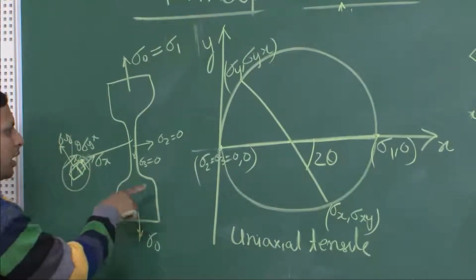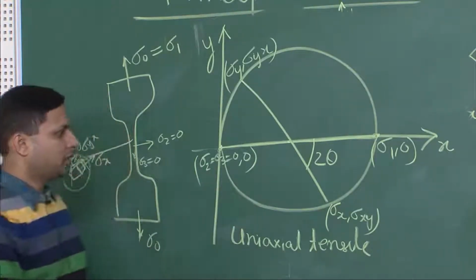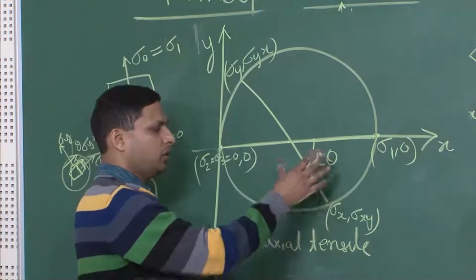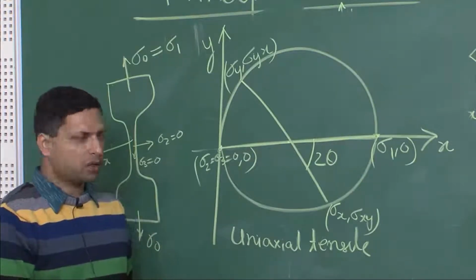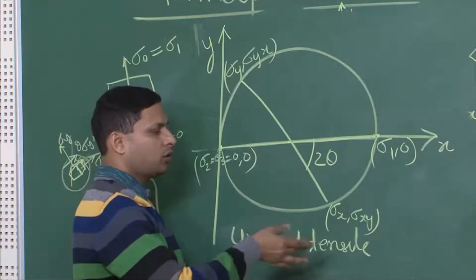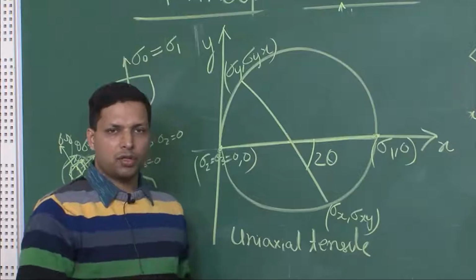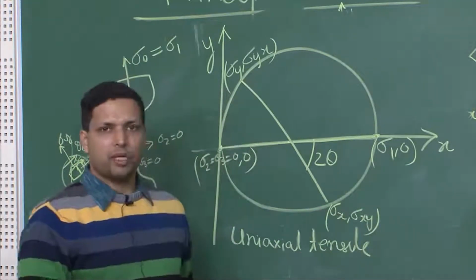So, we are able to extract so much information from this Mohr circle just by looking at it, and by simple construction we are able to get not only the stress values at different orientations, but also their magnitude and sign. We can also work it backwards: when we have a condition of normal stresses plus shear stresses, we are able to get back to the principal stresses.